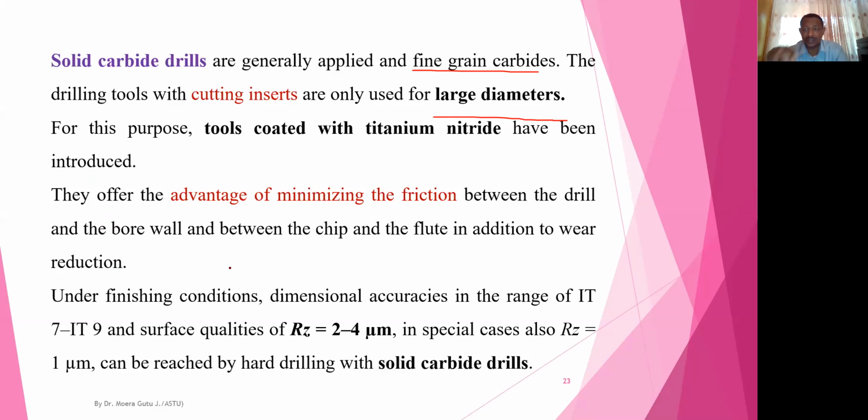The friction imposed during machining, because the revolving drill bits can produce high temperature, and high tool wear can be produced. So to reduce high tool wear of the cutting tool, the friction coefficient or the friction force should be reduced. For that, coated titanium nitrides are very useful because coating can reduce friction resistance of a material.